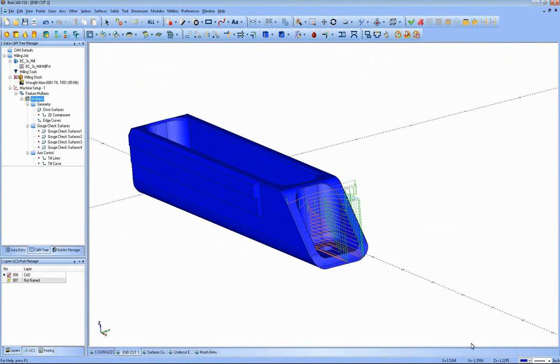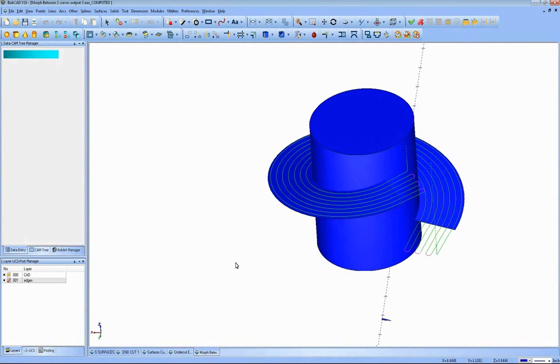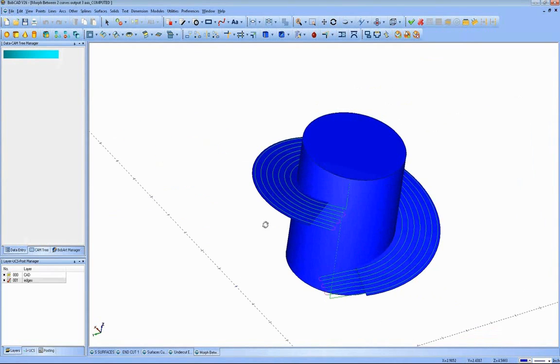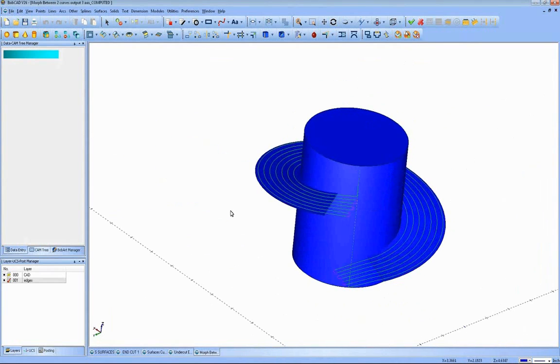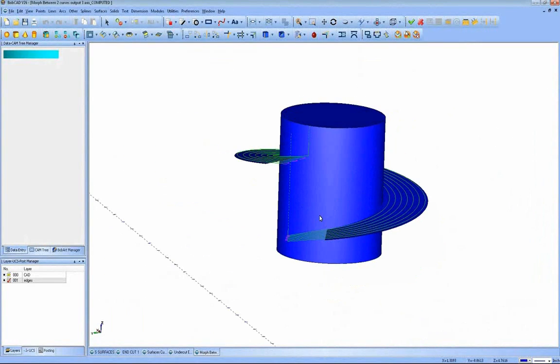Another example of this is this type of a cut here. Now what this is, a shape where you might want to just run around this, stepping inward, cutting this ramp out. And without these tool paths, you would have to get the intersecting edge of the two surfaces, create your own offset of the tool, because the tool path, with you drawing your own tool path, won't do any offsets, and then copy it over and use the 3D project or 3D engraving tool path to cut that out.